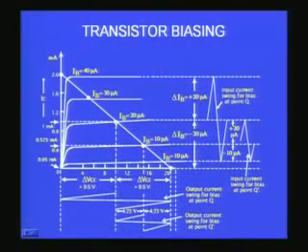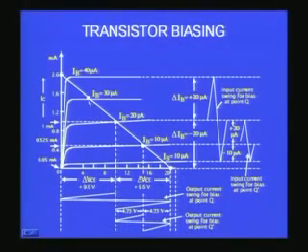So when the base voltage together with the AC applied voltage increases, I will move along this line and go to maybe a new position corresponding to IB equal to 30 microamperes. And when I go down, I will come below that chosen operating point Q to a value, for example, 10 microamperes. That means my current of 20 microamperes is going to vary plus or minus 10 microamperes due to the AC signal that I applied, which is understandable. When the base voltage increases, base current also should increase. When the base voltage decreases, base current decreases. So you find my Q operating point will start shifting when I apply an AC between IB equal to 10 microamperes to IB equal to 30 microamperes, even though at the beginning when there was no AC voltage applied, I was at IB equal to 20 microamperes.